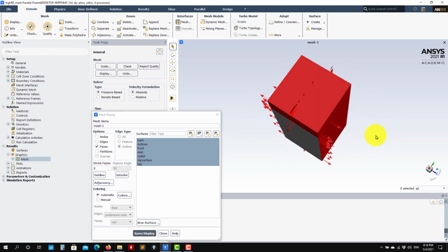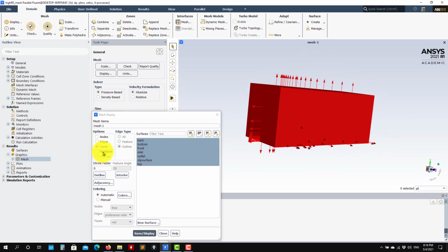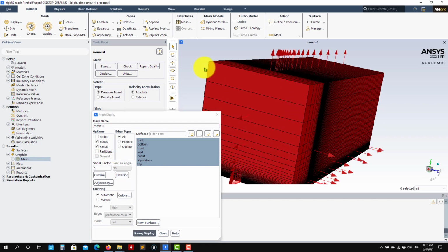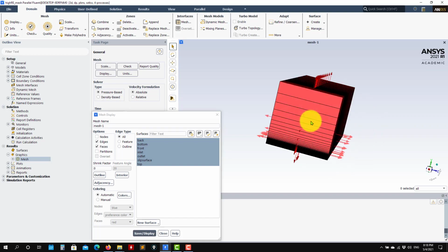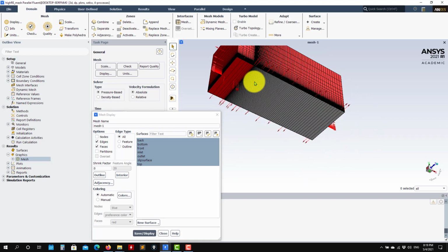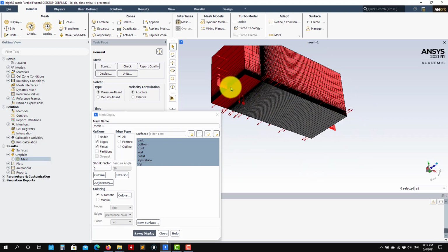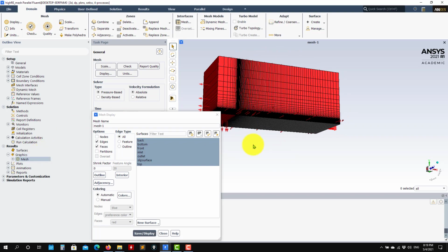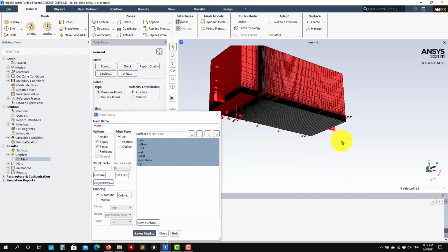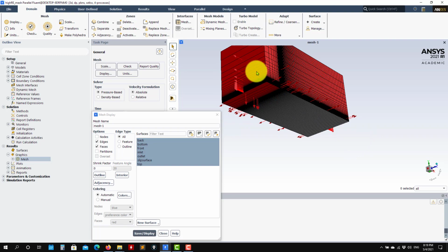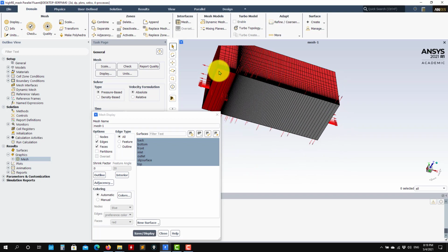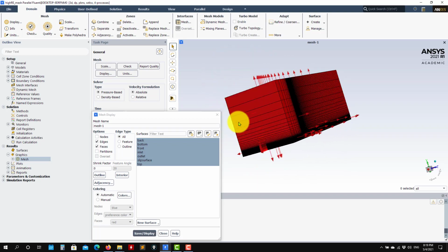And look at that, this is a pseudo 3D case in the sense that if I plot the edges, you see that I have only one cell in this direction. I like to work like this because visualizing quantities at these surfaces is easier. Instead, if you have the 2D case that is a surface, you need to plot the lines, and sometimes that can be a little bit confusing. So here you can visualize things better. It is perfectly equivalent to a 3D case. Nothing changed, only that you have one cell in this direction.